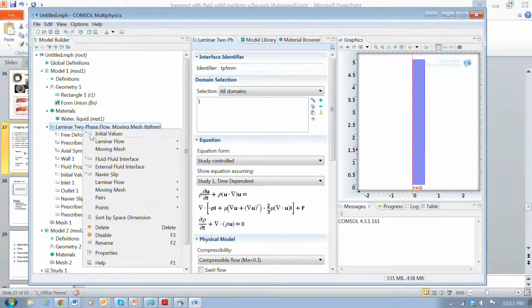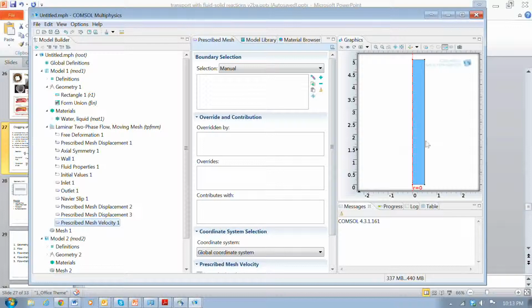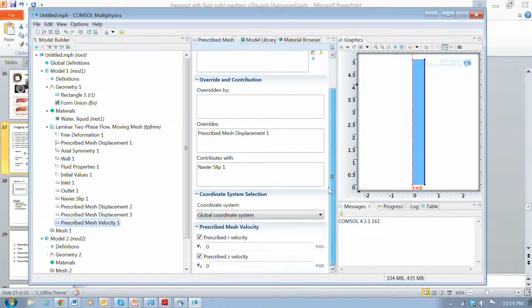And then the last boundary condition we need is the mesh velocity. We'll prescribe the mesh velocity on the outer wall. This is the wall that will be moving as we have deposition occurring. And so what you want to do is select boundary system for the boundary here, and you'll get T1 for transverse velocity, and that we're just not going to specify. The normal boundary we will specify, and we'll just set it equal to 0 for now. Okay, so that should run.